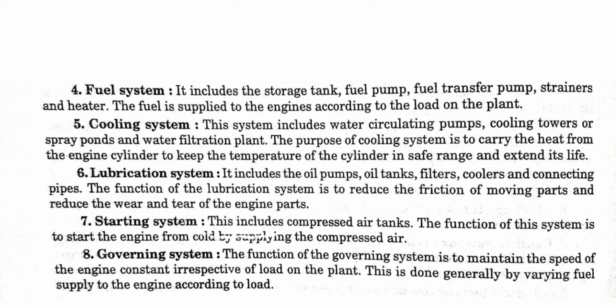Sixth component is the lubrication system. It includes the oil pump, oil tank, filters, coolers, and connecting pipes. The function of the lubrication system is to reduce the friction of moving parts and reduce the wear and tear of the engine parts. Seventh component is the starting system. This includes compressed air tanks. The function of this system is to start the engine from cold by supplying the compressed air.